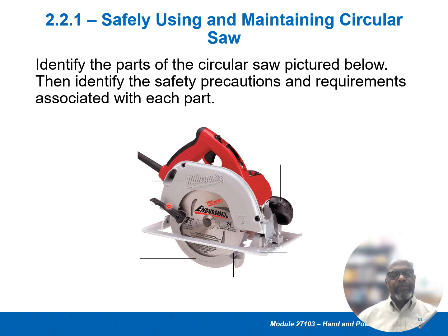But again, keep your fingers out of the way of a moving blade. As a matter of fact, keep the power cord clear. It's a cutaway, so you don't see the whole power cord, but make sure the cord is not getting pushed over the blade when you're cutting.